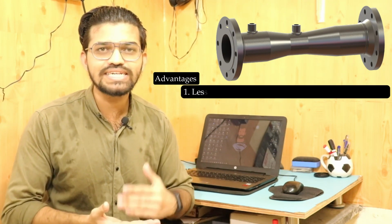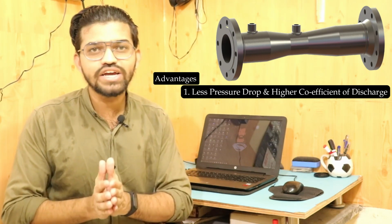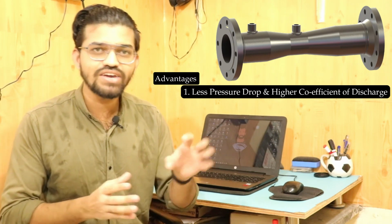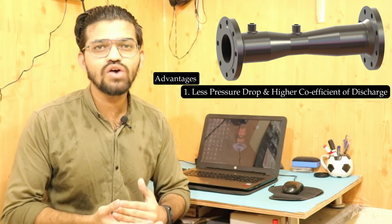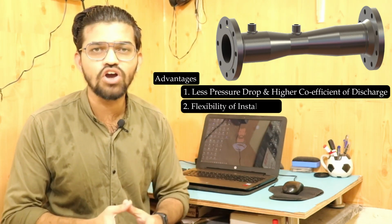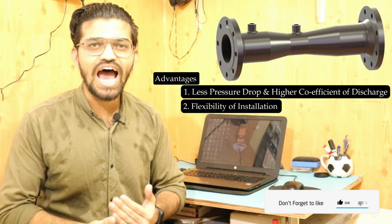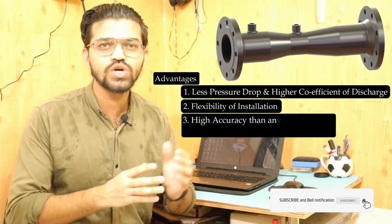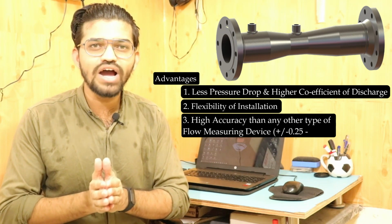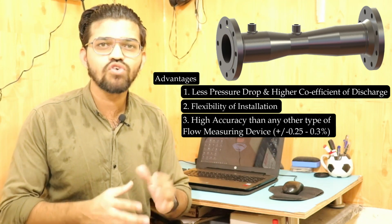So let's see some of the advantages of this Venturimeter. In the Venturimeter, the pressure drop is less and it has a higher coefficient of discharge. That is another advantage we get. Also, this Venturimeter can be installed horizontally as well as vertically, so we get flexibility of installation. Also the Venturimeter has high accuracy, between plus minus 0.25 up to 3%. So it has higher accuracy than any other type of flow measuring instrument.